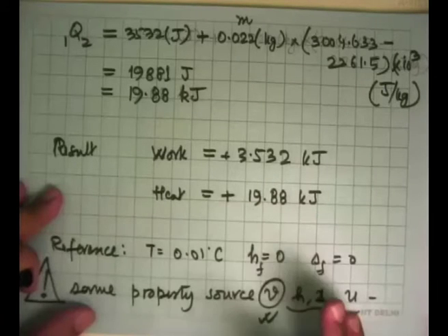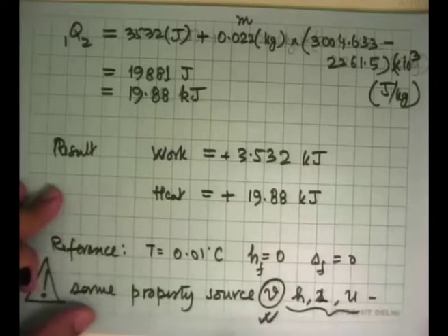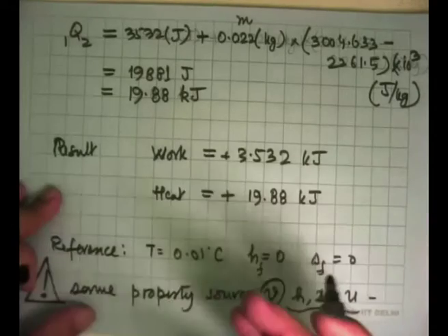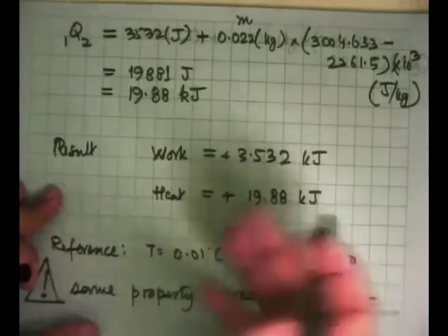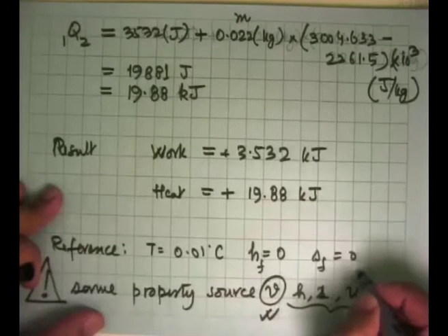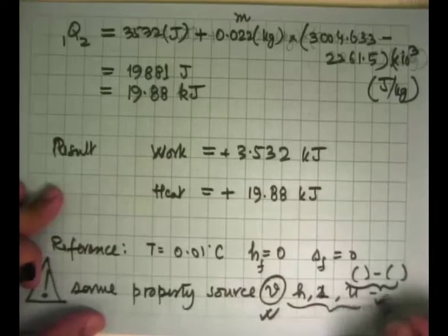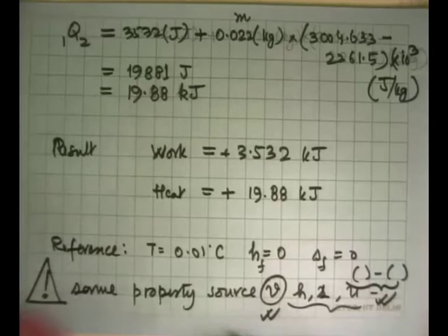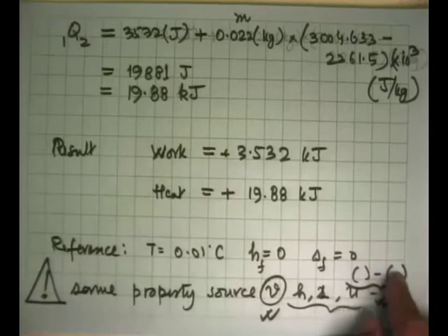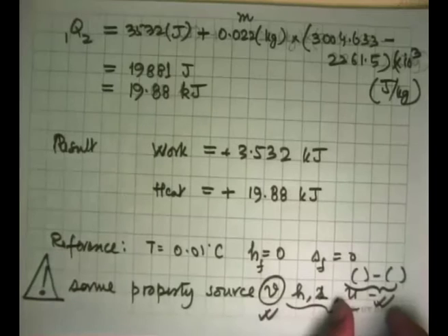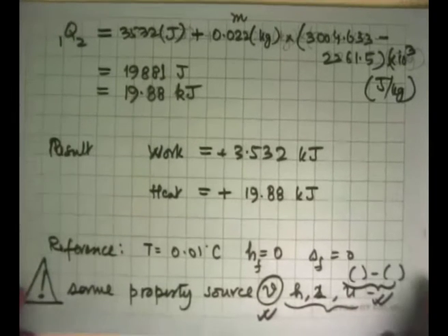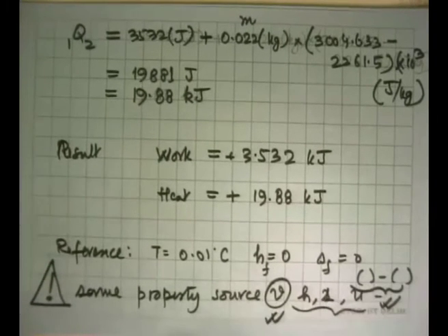These will be different, but don't worry too much about it, because in most of the problems, whether it is heat transfer or work transfer or say a throttling process, we are always dealing with the difference of two properties, and the difference of two properties will be pretty much close to one another irrespective of what the reference temperature was. So you could have slightly different values of individual properties, but the difference in the properties will not be very much. So don't worry too much about it at that point. The difference should be matching with what we have.